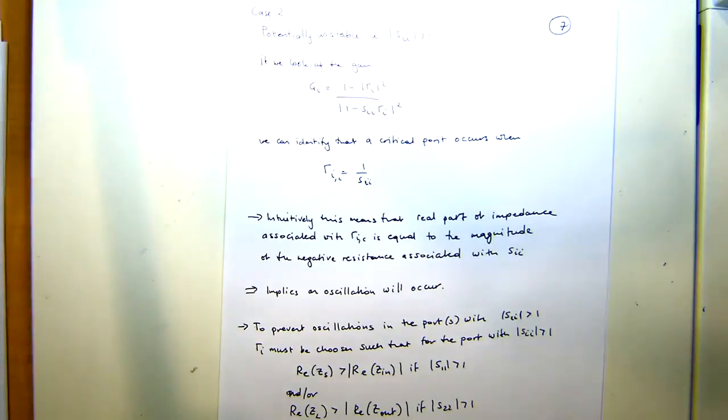Conservation of energy doesn't apply in the simple sense, it applies only if you consider the rails in your supply also. But if you've got a passive network and you put 1 watt in, you can never get more than 1 watt coming back out at you, no matter how badly it was mismatched. It'd be a maximum of 1 watt. But if you've got an active network, those values can be much greater than 1. Nothing stops them from being greater than 1.